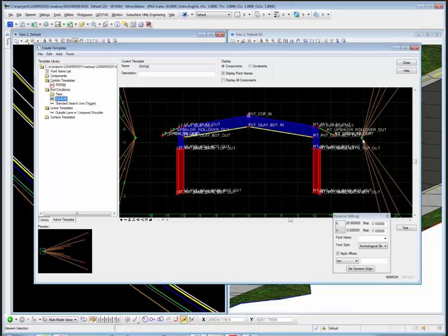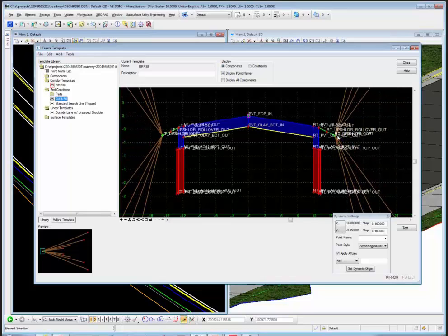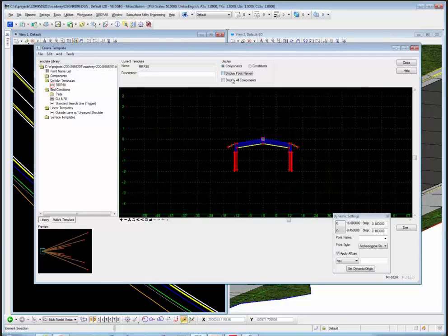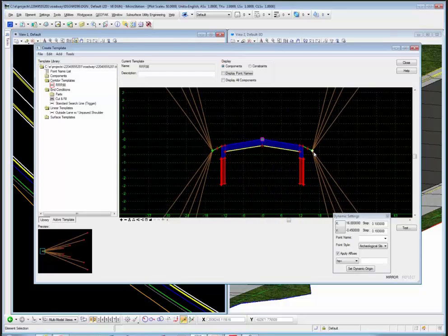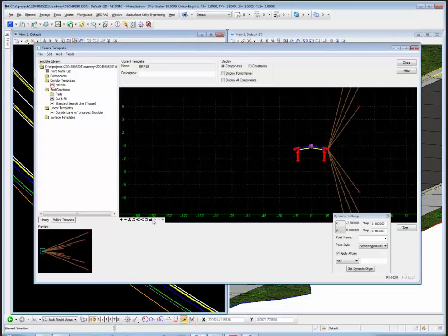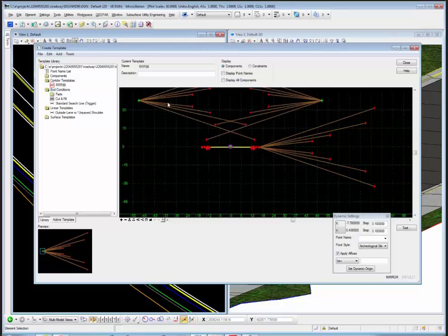And again, if you fit it, then if I needed to put end conditions on here, I could come over to my end conditions folder and just grab the standard end conditions and drag it with the mirror option. Notice that the mirror is darkened over here, where reflect and mirror. You could basically reflect and mirror at the same time. So I'm going to place those on the unpaved shoulder point. Let me Control Z. I didn't like the way that placed in there, so let me try it again. I'm going to drag and drop this and put it on the end and merge it with that point right there. And I don't know why the other one is not there.